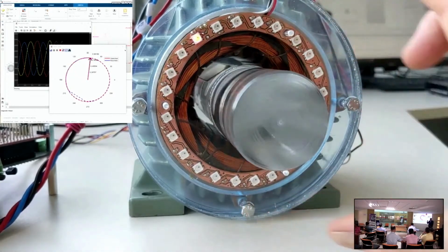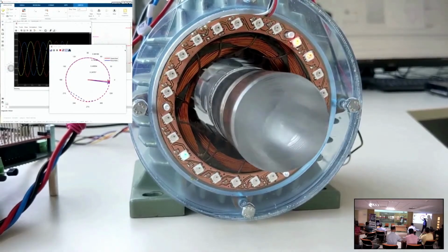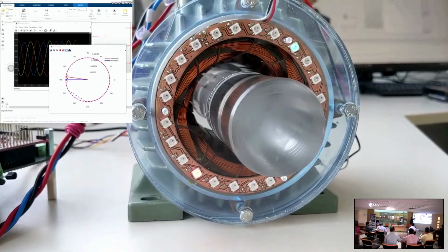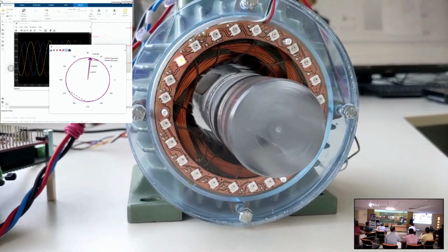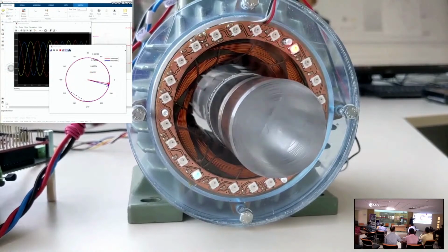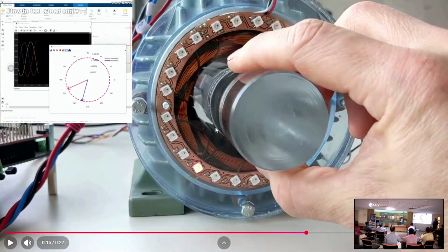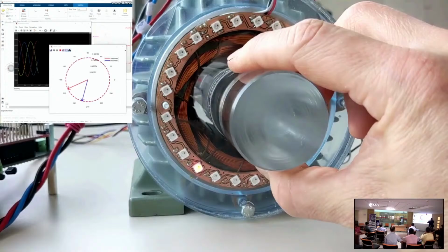Can someone recollect, sir? We discussed this, right? This angle between the stator magnetic field and rotor. Physically, that angle should not become zero. The stator and rotor magnetic fields try to align. That angle is delta. Delta should not become more than 90. Delta should be between 0 and 90. Right. So that is what he is showing.